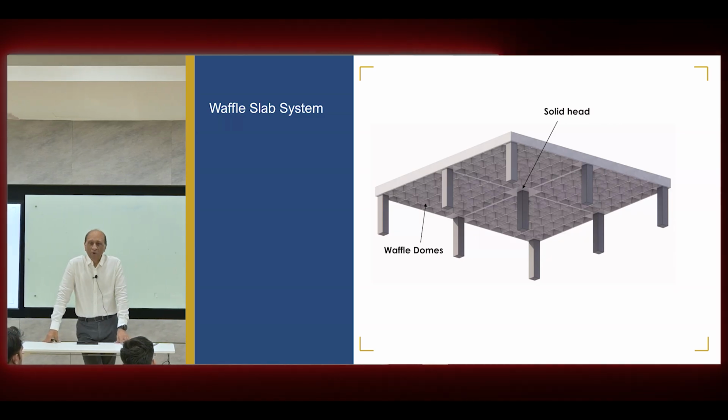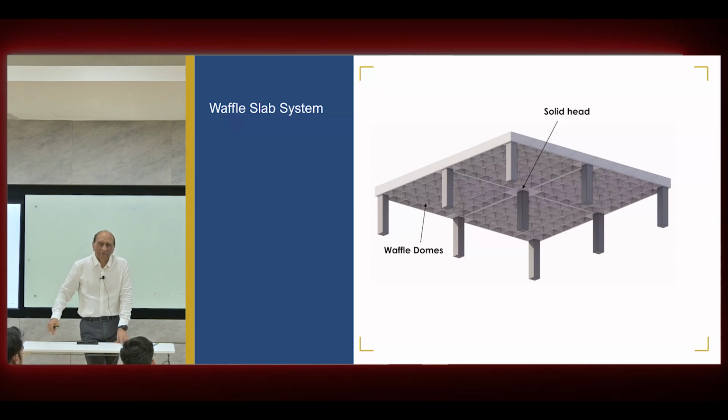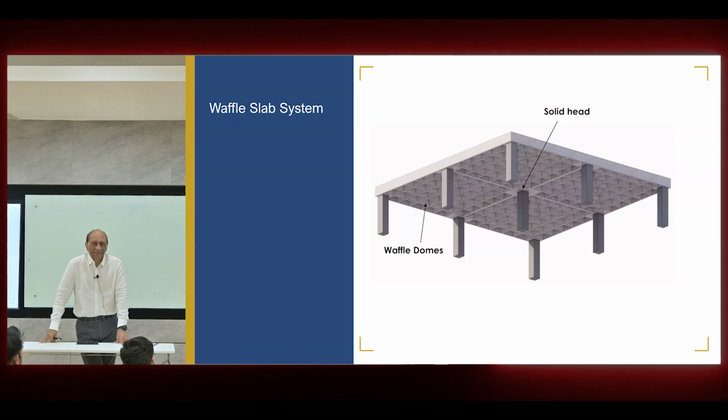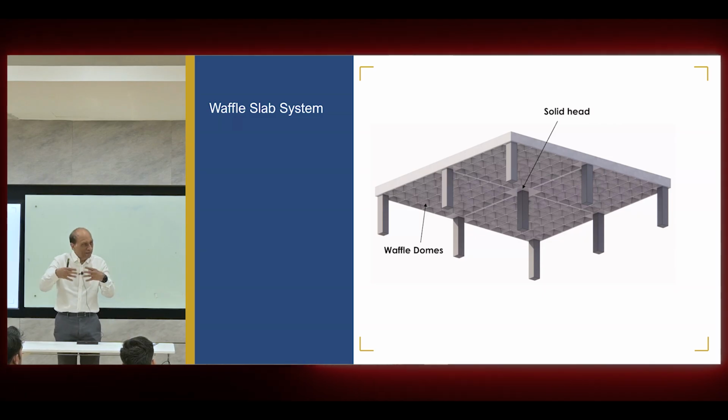But the problem is formwork. You know, it was difficult, a lot of fabrication, a lot of reinforcement stuff. And you know, in the beginning, in the 80s, I used to use a lot of this in my projects. We used a lot of waffle slab. And there were a lot of contractors who made those forms from fiberglass, which had just come in. They started to make the fiberglass pans and reusable.